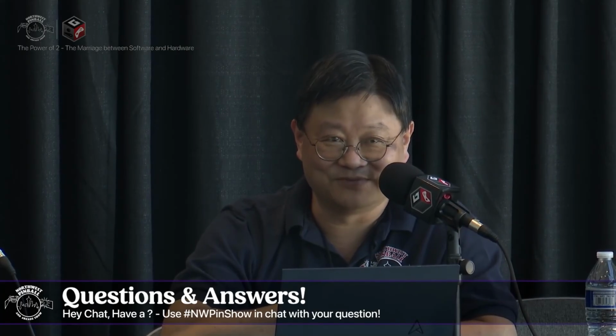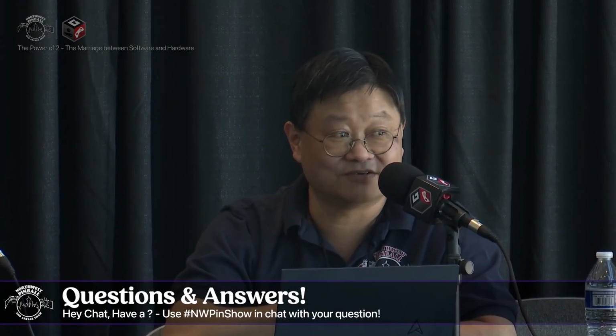So what the hardware people do is they say, oh, you've entered indeterminate voltage territory, reset. And by doing that, it resets the system back. And often the indeterminate voltage territory is entered because of too much of a load on the system. You've drawn too much current somewhere. So the easiest way to restore the load is to stop the software from executing, which withdraws all the load, and boom, everything comes back up.